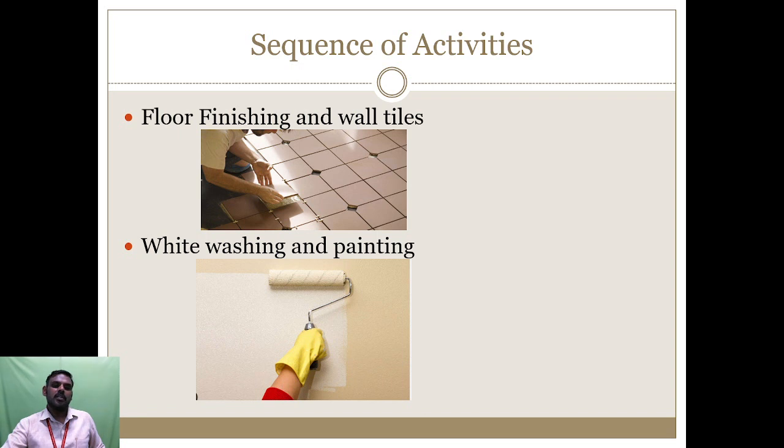Then flooring, finishings and wall tiles. This is done as a water stopping element utilized in the restrooms. In the restrooms, the bottom tiles are laid in a rough finishing manner. It's like a matte finish, so that skidding will not happen.